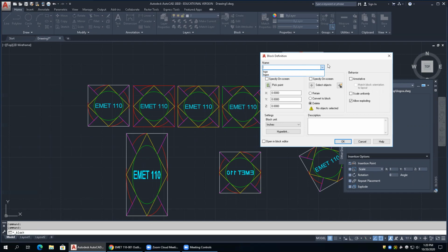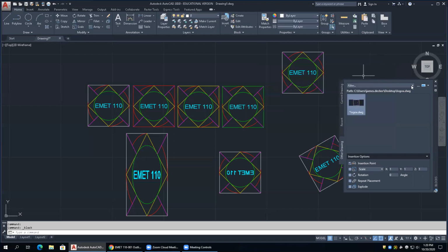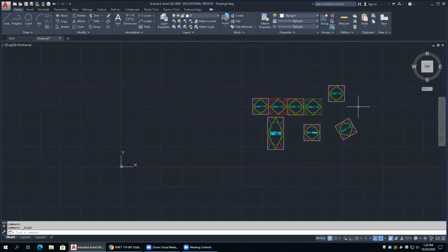Okay. So insert's cool because you can insert blocks internally, or you can insert DWGs externally. Okay. W block is the reverse. W block allows you to export blocks, export objects, or export the whole file. Okay, pretty neat. All right, MInsert. MInsert stands for multiple insert. So this is like an array, and it is kind of a limited array.